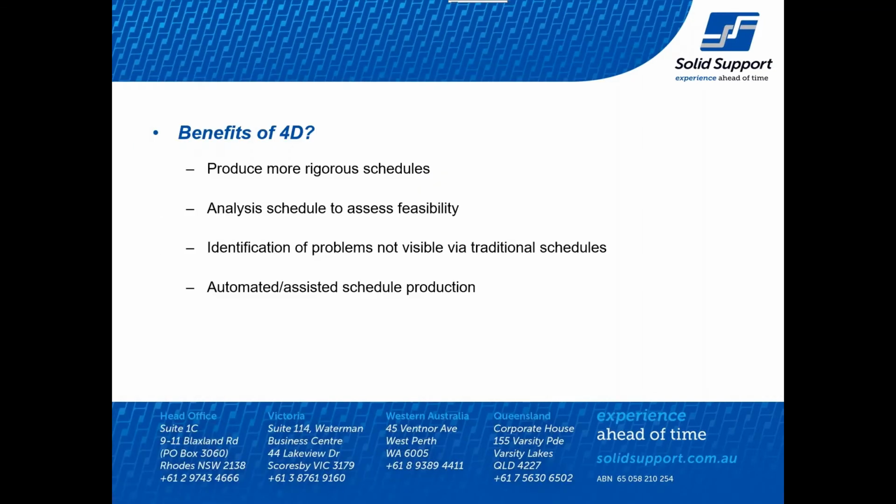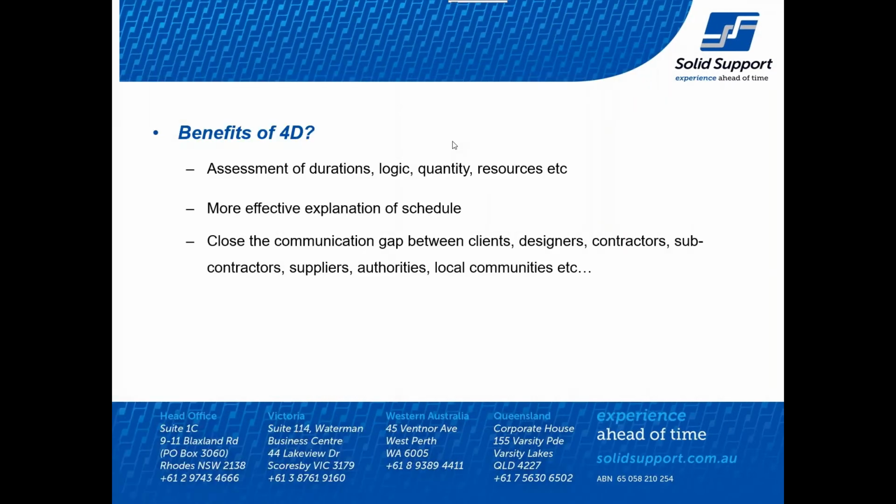So we'll first start with the benefits of 4D. What are the benefits of linking that 3D model to your project plan? First of all, it allows you to produce more rigorous schedules, so you can actually visualize what's happening. You can also analyze the schedule to assess its feasibility. Are you putting something up before the underlying structure is there? You can see if there's something in the way and so forth. We can identify problems that may not be visible in a normal project plan. It also allows you to automate and assist the schedule production, and we'll talk about how that can assist as we go through.